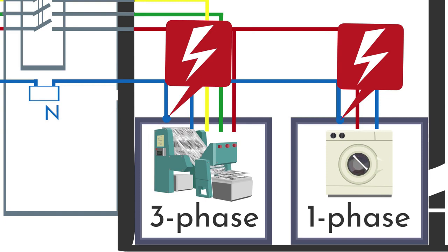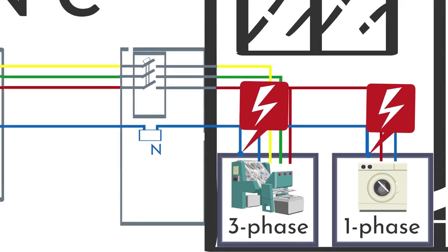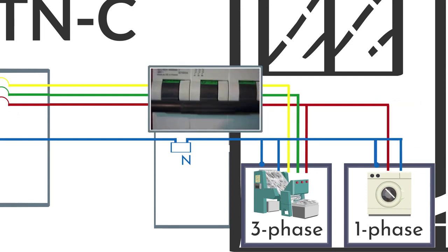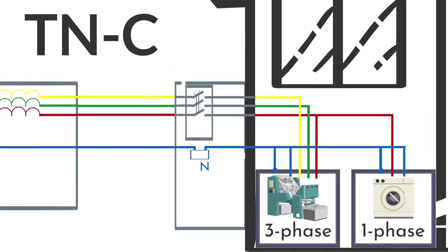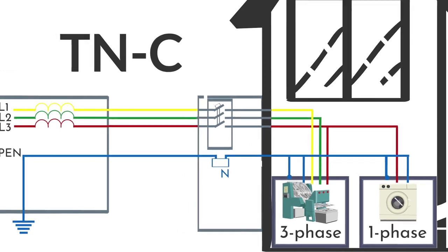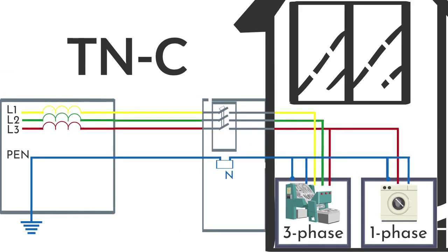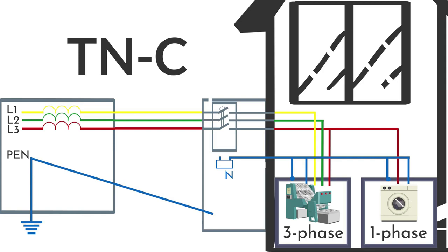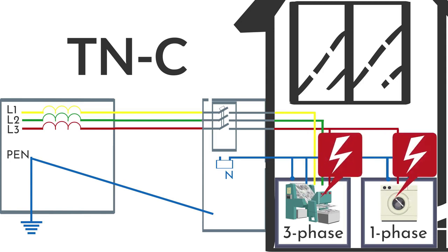In the event of an emergency contact of the phase conductor and electrical appliances enclosures, a short circuit occurs and an automatic circuit breaker cuts off the voltage. It is a widespread system which is used in most residential homes. However, protection grounding is not meant in this circuit. What are its disadvantages? Since the neutral conductor is constantly loaded due to the electric current flow, it can either burn out or break off. Due to the jump of voltage, the appliances often go down and lose their protection grounding.